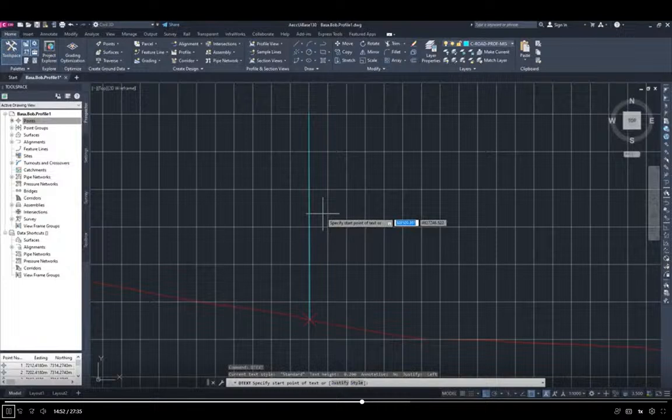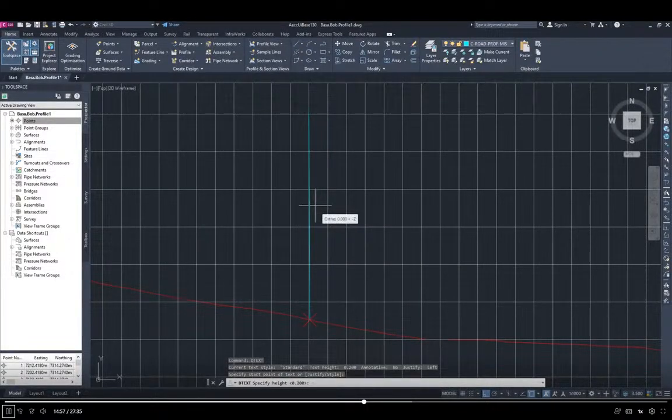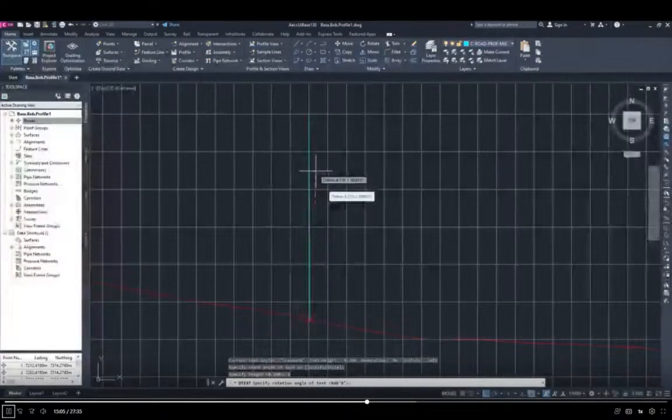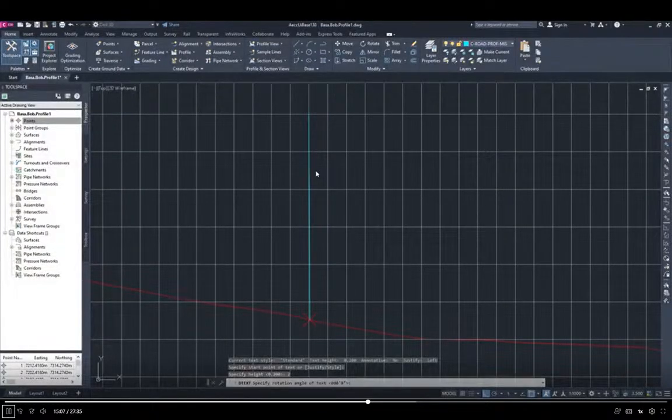Okay, so we're going to find a spot to place it. I'm going to place it over here. The height we're going to do is height of 2. Specify the rotation angle. Now I'm just going to point it straight up and just click. Now we can start typing. So that command to get that center line symbol is going to be \U plus 2104. And immediately it says center line. Then I'm just going to type in caps, Bovine BLVD. I'm going to hit enter. Then I'm going to hit escape. Just going to give it a moment.